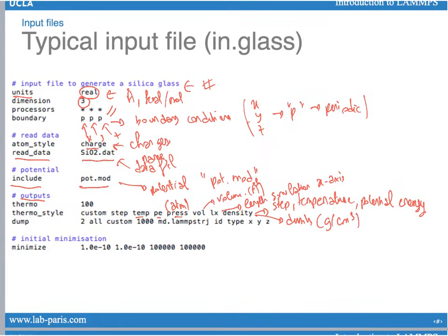Okay, so these are all the thermodynamical properties that you want LAMMPS to give you, and there might be some other options. You might want LAMMPS to give you the enthalpy of the system or any other properties of this kind. You have to put here all the keywords that correspond to the property that you want LAMMPS to calculate. So those are the thermo style properties.